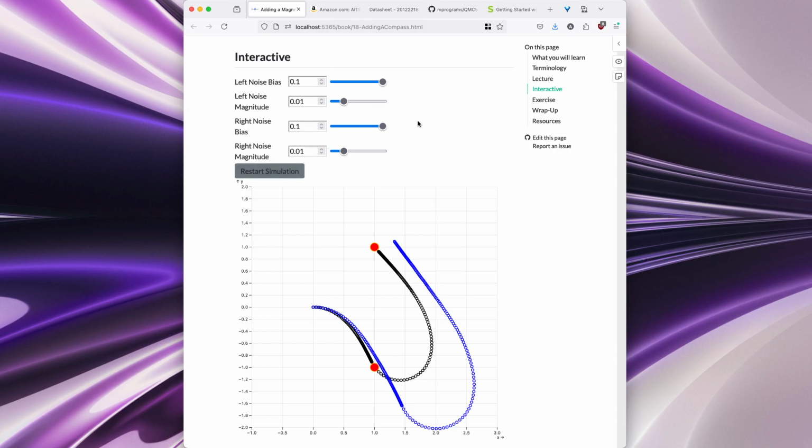All right, well, one way to combat this would be to have a camera mounted somewhere in a fixed location in the room that tracks the robot and tells the robot exactly where it is. That's not always going to be handy, and so there are things we can do to our robot itself that can improve its localization or pose estimation. You'll hear me use both of those terms interchangeably. Normally I'll use pose estimation when I'm not worrying about noise, and I'll use the term localization when noise becomes a bigger and bigger factor, and we need to fuse multiple sources of information for providing an estimate of where we are in space.